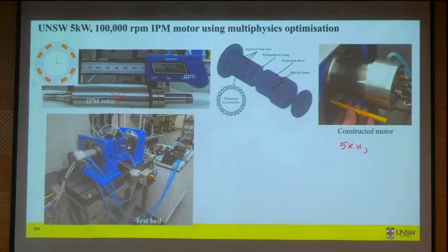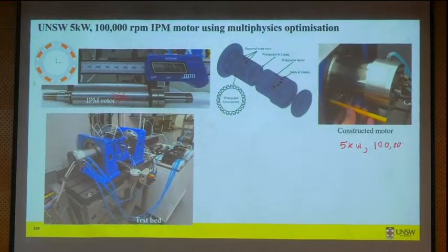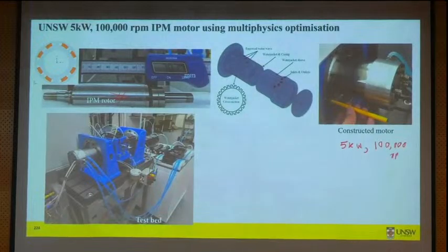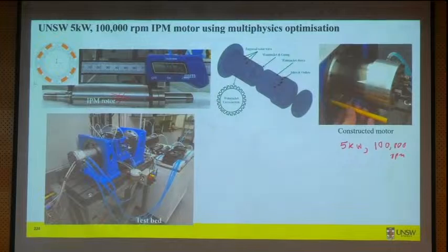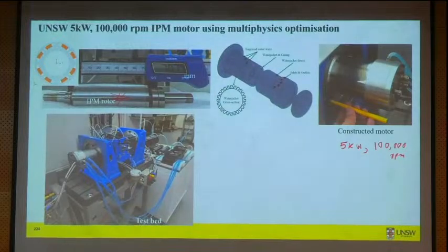There's huge interest from industry for this motor. That's why we are being a little bit careful here, so we are not showing you the geometry. We just use neodymium iron boron, and silicon iron material with the highest possible mechanical stress. So no exotic material, it is all easily available material.